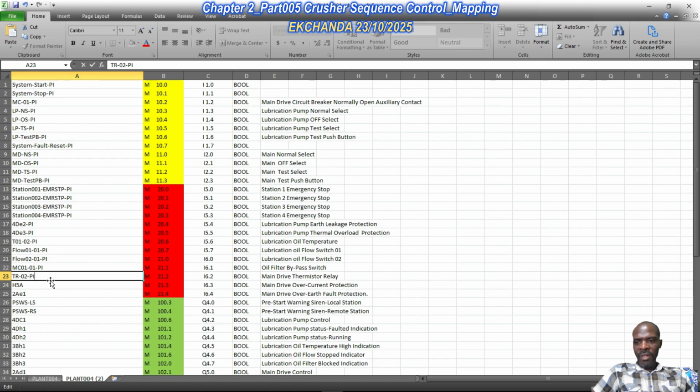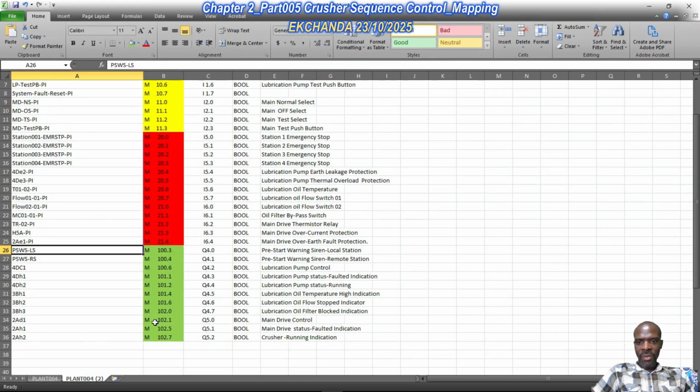Okay, so peripheral means external to the PLC. It's a peripheral input in the sense that this address is pointing to an actual physical unit. Okay, so there we go, like so. And then the ones highlighted in green are peripheral outputs, as in PO, peripheral output. Control C, Control V.